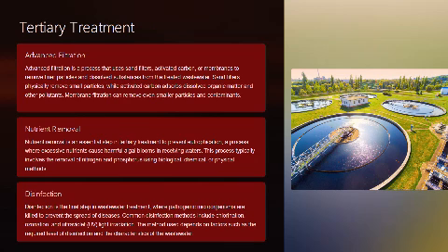Let's move to the next treatment stage, and that is the tertiary treatment. So, three things that you have to recognize. One is advanced filtration. With advanced filtration, what we want to do is remove the finer particles. We started with stages that were removing heavier, bigger particles. But now we want way finer particles to be removed, and we use advanced filtration for that. Specific things that are used are sand filters, activated carbons, or membranes.